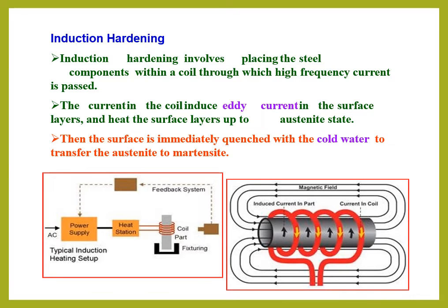Then, after heating, we do the quenching using water. That is the only difference here. We pass high frequency current, the specimen resists the current flow, and it heats to a high temperature within a fraction of a second.